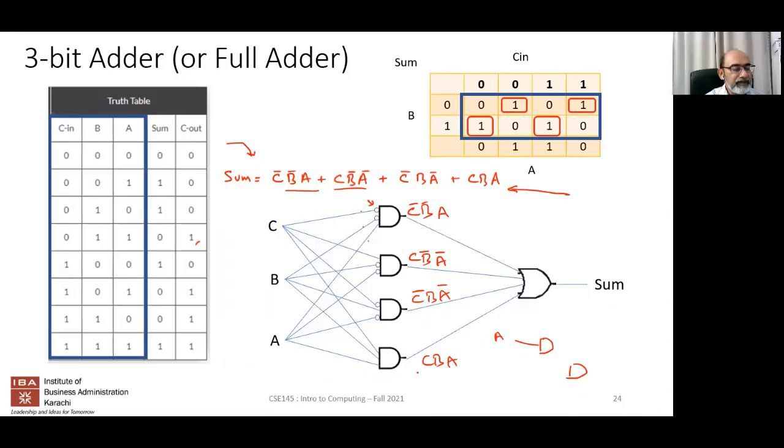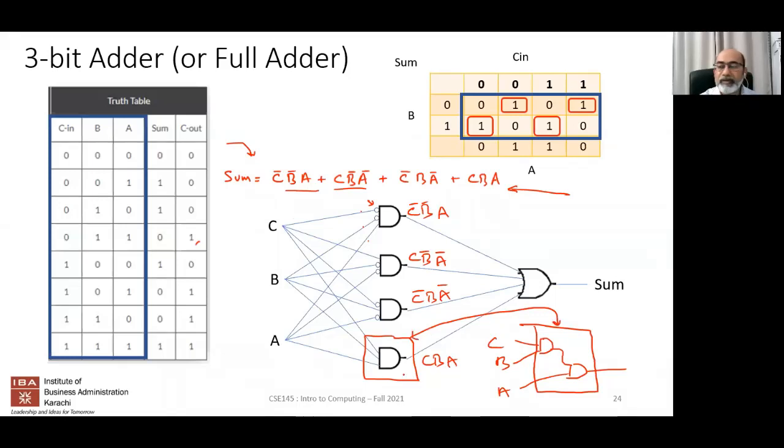So for example, you're looking at this expression A, B, and C. What you could have is something like a C, B, and an A. And this is actually what it's doing: these 2 AND gates together are being used to represent a 3-input AND gate. So basically, when I'm representing more than 2 inputs, it can be thought of as multiple gates together being used to form a single expression.